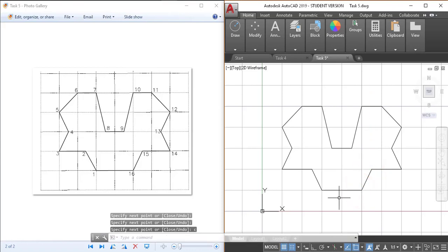So you can see that if you are dealing with very simple drawings and you have a grid available, it is recommended to use snap mode or ortho mode instead of using an absolute or relative coordinate system. In this way you can save a lot of time and draw your drawings quite easily. Thank you very much. In the next lecture we will try to draw some complex drawings using a relative polar coordinate system in combination with a relative Cartesian coordinate system. Thank you very much.